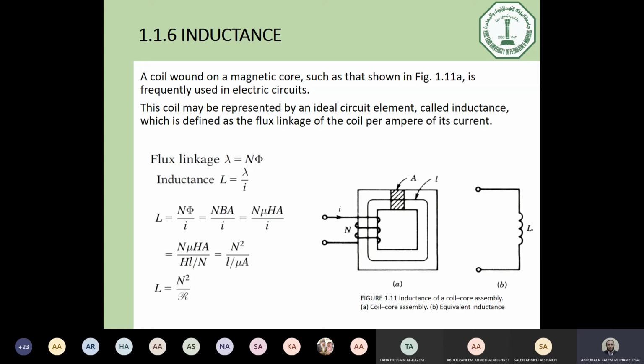Firstly, if I would like to buy an inductance, how can I get it? You know, we can find electrical elements in the market like resistance, like capacitance. However, for a power inductor, not the small one which is made for specific products, but a power inductor that may be needed for a motor, for instance, for any actuator, for any application, you need a high power inductance. How can you get it? Actually, you may not find it in the market. You have to create it or ask a company to create it for you.